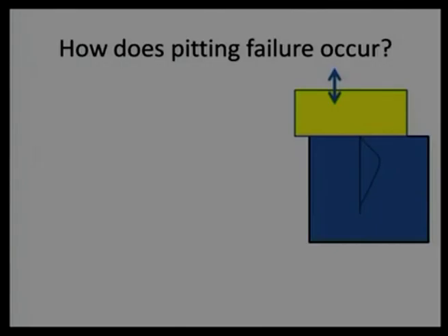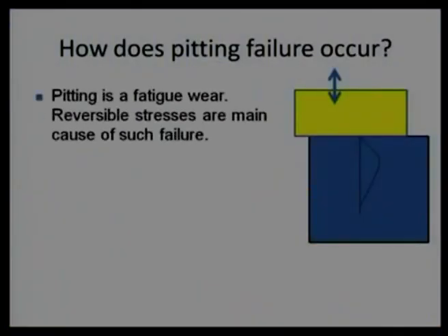That is why many times if there is no surface crack available, fatigue will start from the subsurface, and if there is one crack, subsequently another crack, and they merge together, become bigger in size, unstable, and the fracture will occur. So, keeping this in mind, we are starting.